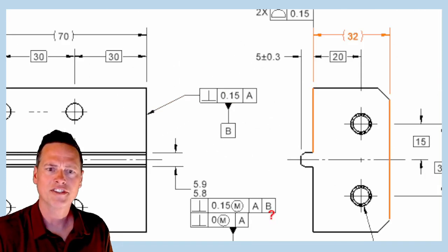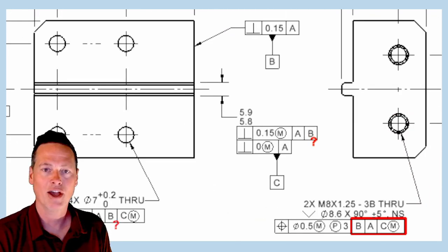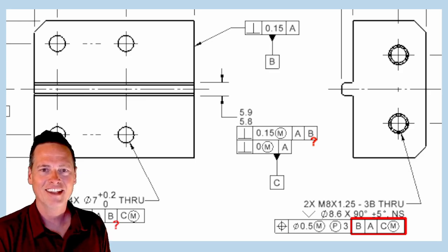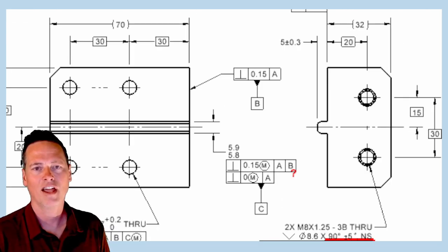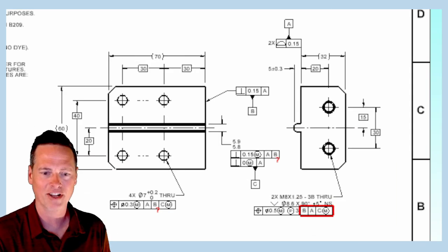Okay. And then the datum C feature is this close tolerance tongue thing. Now I have no problem believing this is a locating feature and should be a datum feature. But it's so long and close fitting that it's likely to be a poor tertiary datum feature. It's likely to over-constrain the part as a tertiary datum feature. And I am not on board with the datum B surface as a secondary datum feature. It should definitely be a primary datum feature for these M8 threaded holes.